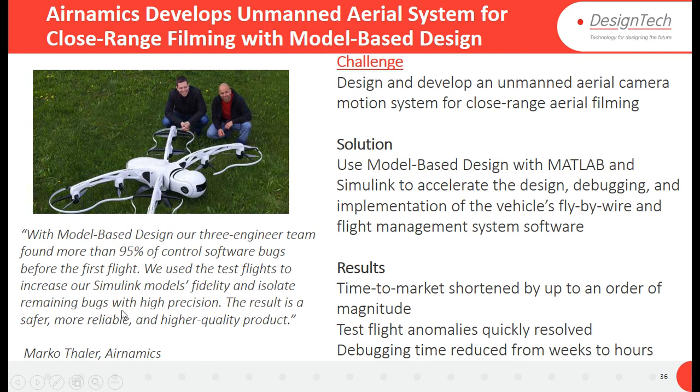And Mr. Marco told us that with model-based design, their team of only three engineers found more than 95% of control software bugs before the first flight. We use the test flights to increase our Simulink models' fidelity and isolate remaining bugs with high precision. In MATLAB, it's not only that you test the model; MathWorks has different licenses to test for bugs in the generated code, like Polyspace Bug Finder and Polyspace Code Prover. We can use Polyspace to test whether there are bugs or not.